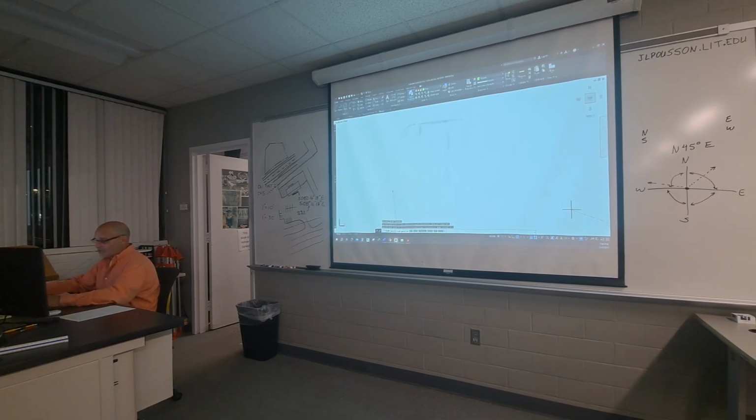My next side, once again, at my distance, 450 feet is less than my angle, north 23 degrees, 16 minutes, 18 seconds west. I'm gonna check this one just to make sure. Hit enter.